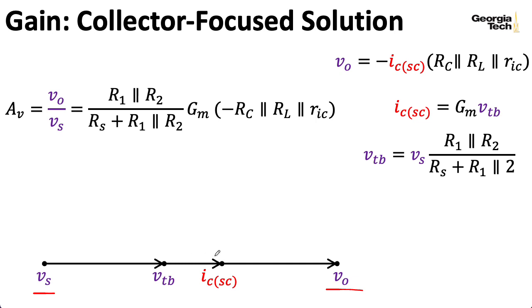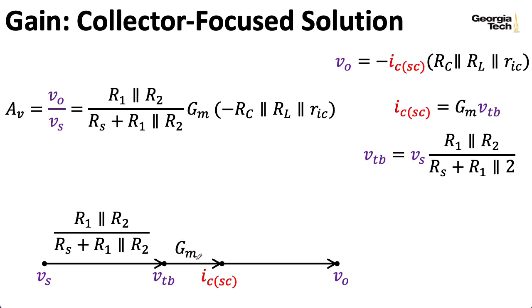And we have some intermediate variables in between. And then for each of the arrows, we're going to draw the constant we need to multiply by in order to get the next element of the chain. So this isn't really necessary for what we're doing right now, but this Mason flow graph idea comes in very handy when analyzing feedback amplifiers and you wind up with loops in the graph. So I like to introduce them now just to start getting you used to looking at them.